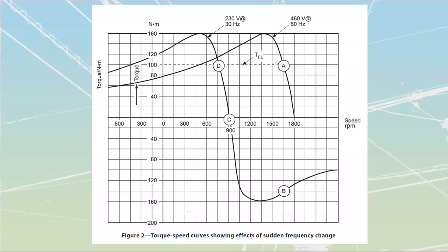Now, when we took a look at the inverters that we had earlier, when we were looking at those H type of bridge inverters, we saw that anytime we were collapsing those lines of flux, we're able to drive back through those diodes on the system back into my main buses. And because we are going to put it back onto the DC, it's actually really, really simple for us to do regeneration.